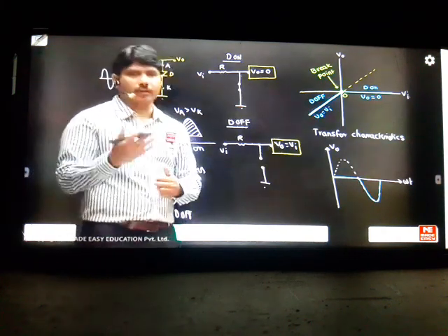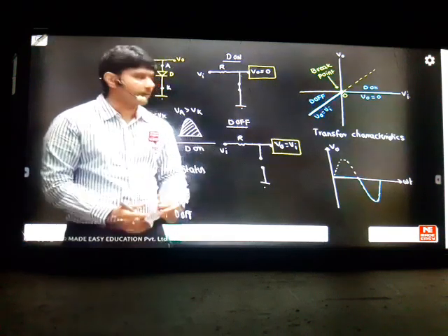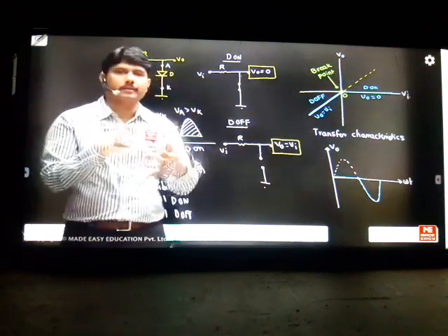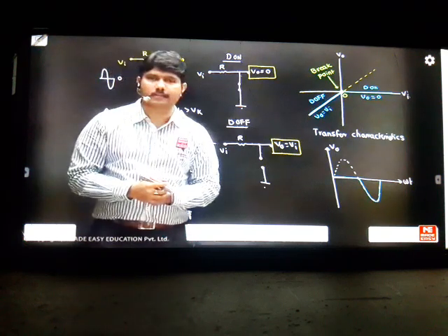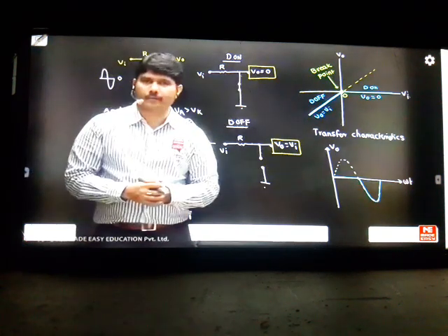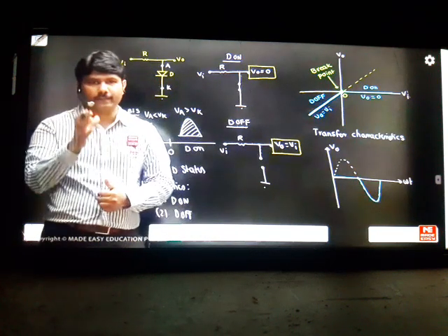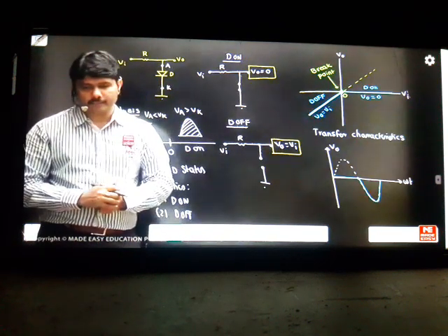Yes, the breakpoint is just to confirm whether the reference I have taken is correct or wrong. This breakpoint will tell in the graph. It will decide correctly, because sometimes the reference voltage I write by seeing the board can change when using meter circuits, which will come in the next point. That's why generally we take a reference point first roughly, estimate it, find the breakpoint, and then confirm it. Initially don't confirm it. Take the reference first, analyze it and see the answer.